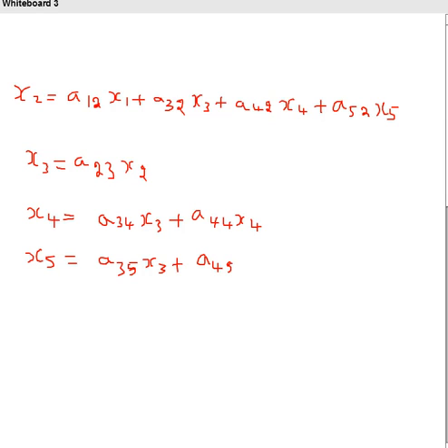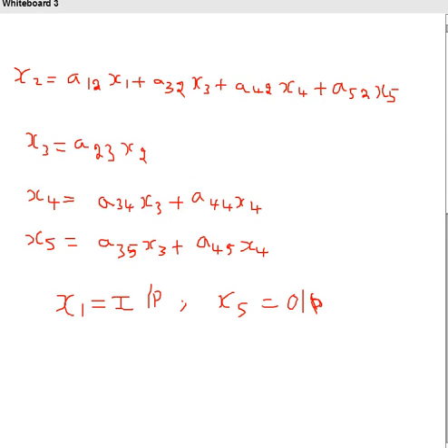So from equations, first construct the signal flow graph. The first step is constructing a signal flow graph. Next we will find out how to find the gain also. Overall gain is nothing but the transfer function. From this, x1 is given as the input variable and x5 as the output variable. So first, how to construct the signal flow graph.